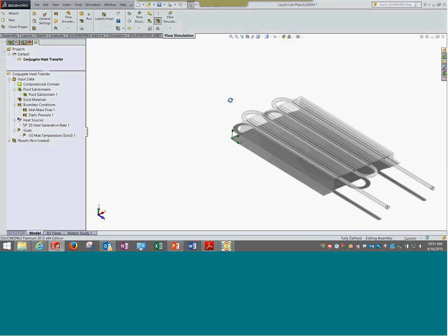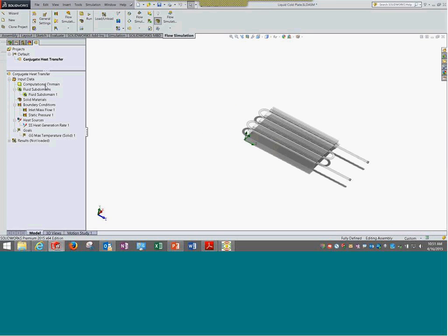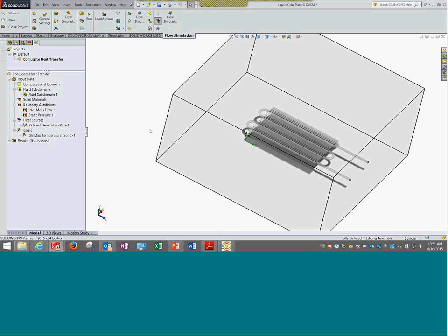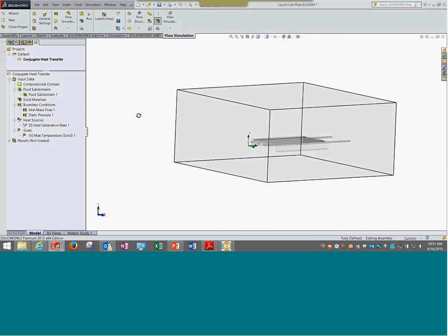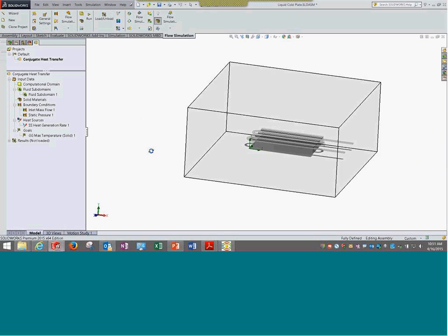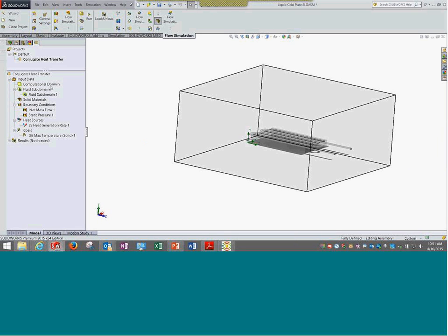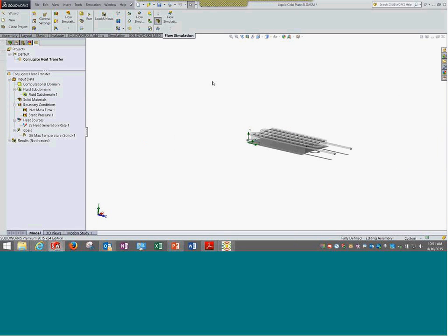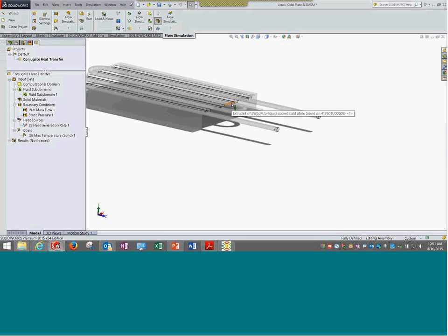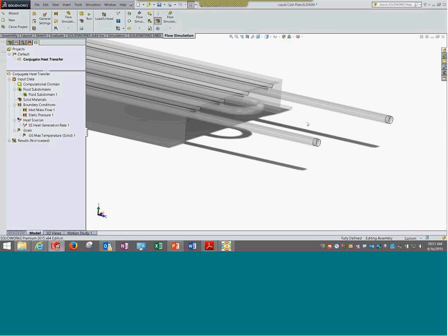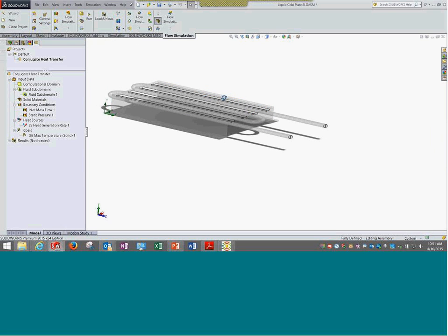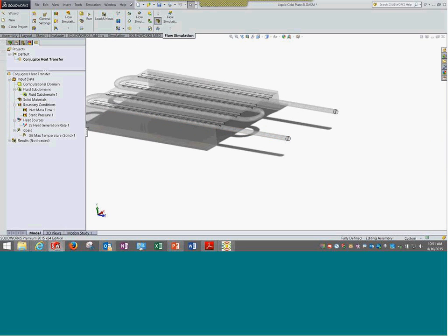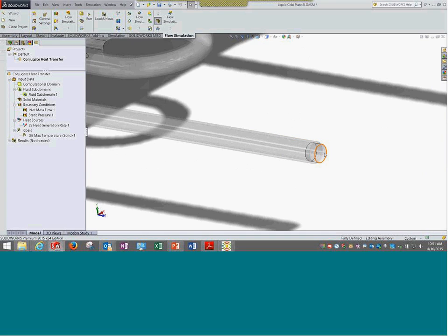So this is it. And the most important thing is the way the fluid subdomain works. Let me first show you this. First of all, as this is an external flow analysis, it looks something like this. A big domain is created which is acting as the external environment. Second, one more domain inside this pipe. Wherever the flow is happening, we need to create lids, so there is a domain where an internal flow is happening, represented inside this pipe.